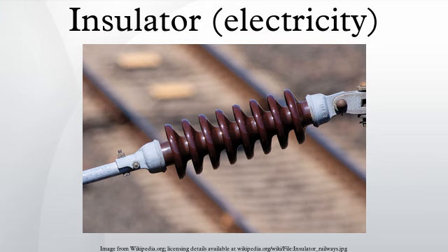For the dimensions of the guy insulation, static charges on guys have to be considered. At high masts these can be much higher than the voltage caused by the transmitter, requiring guys divided by insulators in multiple sections on the highest masts. In this case, guys which are grounded at the anchor basements via a coil, or if possible, directly, are the better choice. Feed lines attaching antennas to radio equipment, particularly twin-lead type, often must be kept at a distance from metal structures. The insulated supports used for this purpose are called standoff insulators.